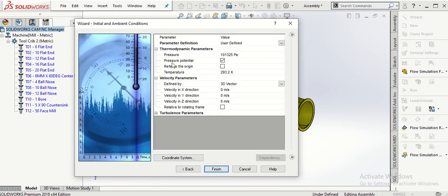So as we know, the parameter is here, as shown, that my assembly is going to move in the y-axis, so I need to change the y direction to -100.